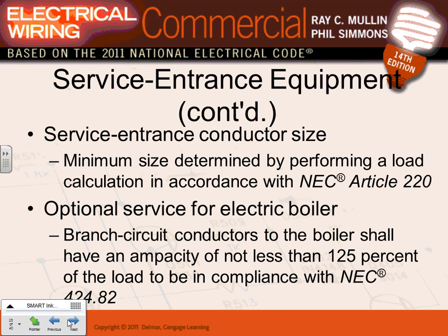Service entrance conductor. How do you size a service entrance conductor? I hope you guys know better than anybody else, because remember that article here? We did it exactly based on this article. You guys have done it for the 500 amp panel for me. Optional service, electrical boiler. Electrical boilers, if you bring a service for them, you treat them as a continuous load and size it based on that. Electrical boilers are so huge, guys. You take the amps of the boiler, increase 25% for safety, and size the service as a direct service to it. That's what they're saying here.